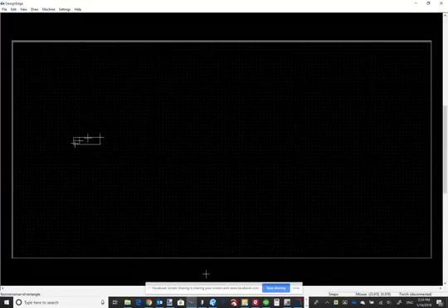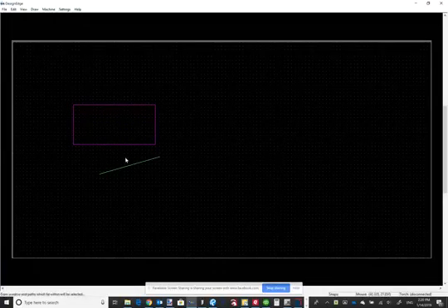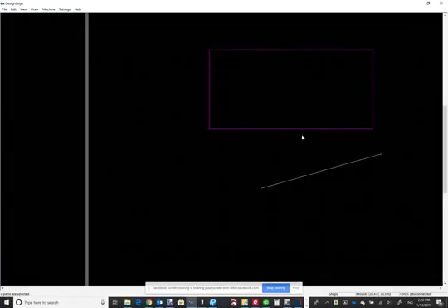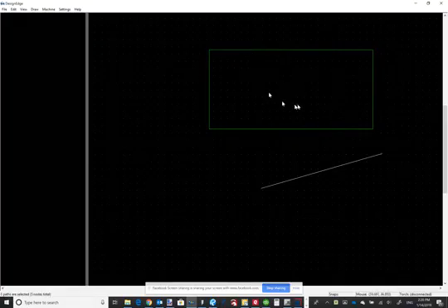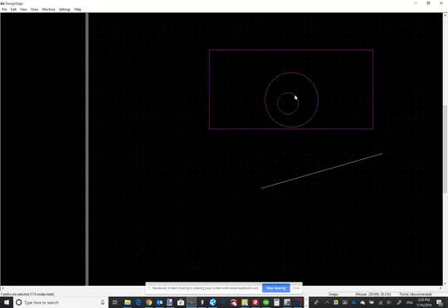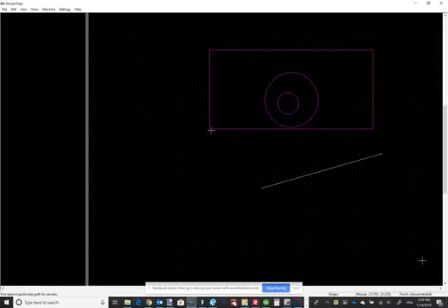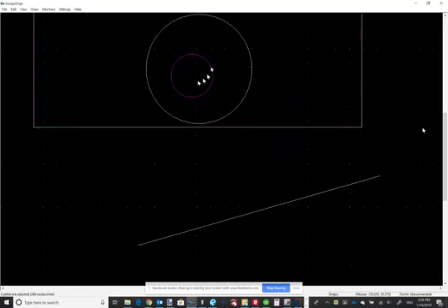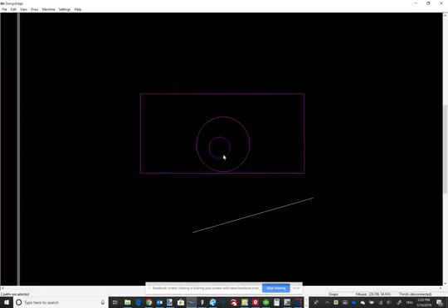You do not have the ability to show solid closed paths. So you're stuck with looking at this being a solid path. So if you cut that out, that's going to be a solid piece. And if you tried to cut that, when you convert that to a cut path, it's not going to convert this middle one because that's an island out in the middle. And it's a little harder to see that without advanced design because you cannot turn that on, nor can you show wide cut paths. Okay, you can still do the show grid with the black check mark, so you can still scroll through that until you get it so that it'll show grid everywhere.